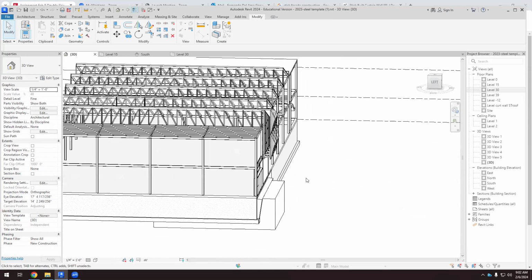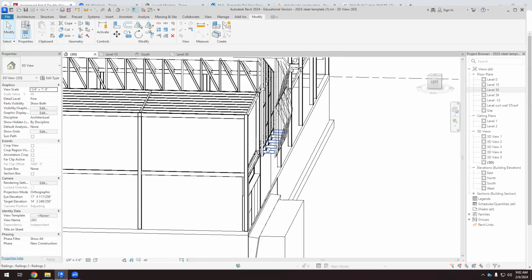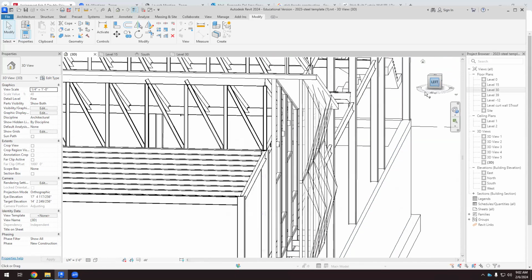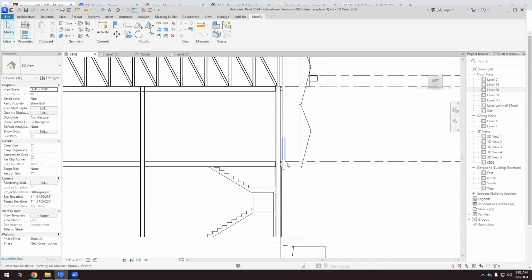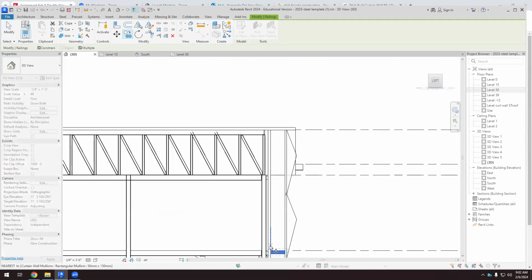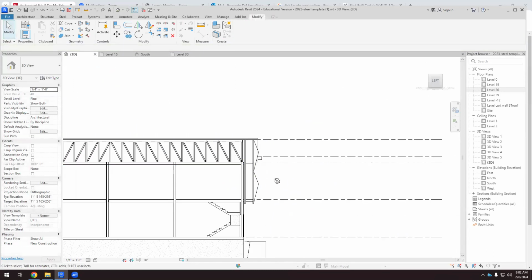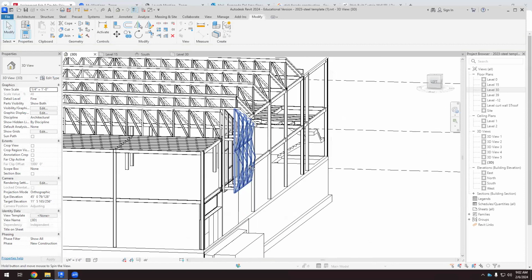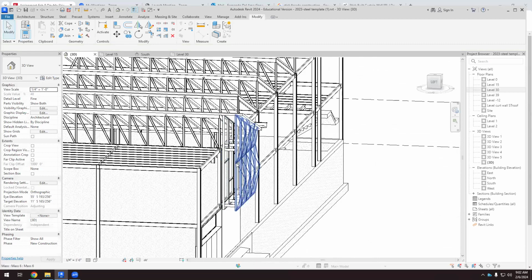Okay, so one connection will not be enough. So I'm going to connect this. So I'm going to copy all these connections. Copy. Remove the constraint. And I'm going to go up. And I'm going to connect it twice. Okay, so here and there. So there are two connections between the first and the second skin.